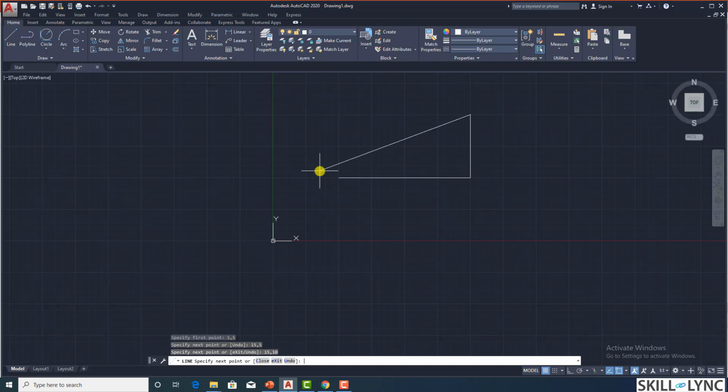Going in the next direction, again specify your X in absolute. You are coming back by 10 units, so from 15 you have to come back to 5. So it is 5 in X and Y remains the same as the previous point, so 5, 10. And you have to close back, so entering the original point 5, 5 and then clicking on enter again to terminate it.